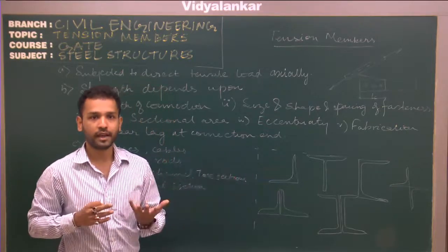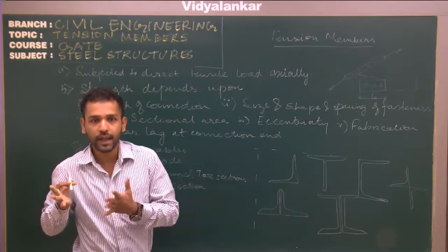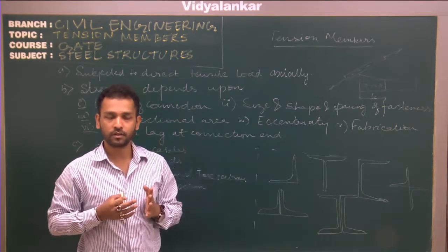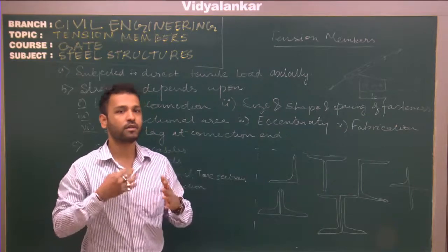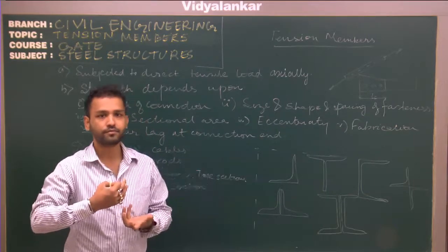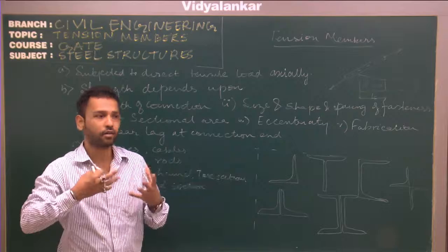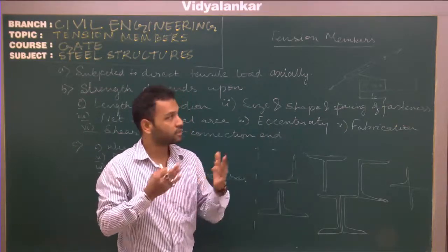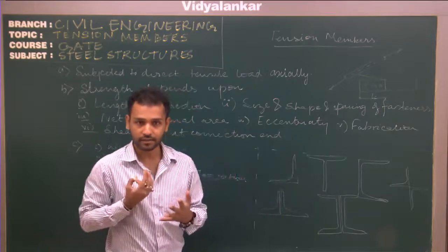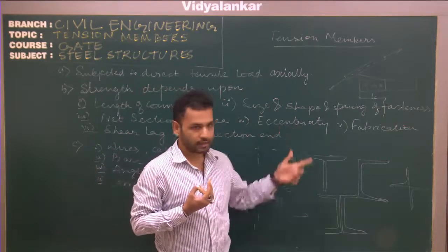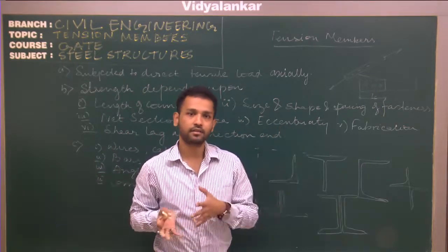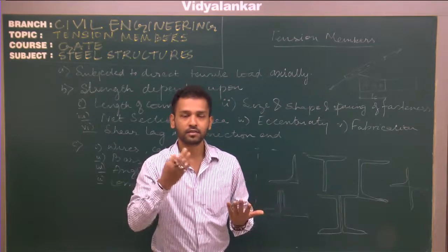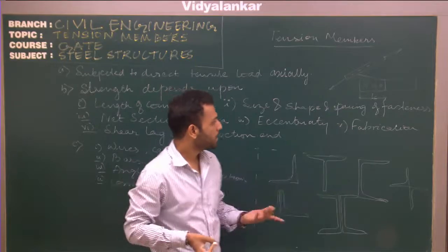If that moment is high, that means an extra load has been imposed on the structure apart from the vertically applied load. That is the eccentricity. So therefore, load plus the moment, so external additional load. If the eccentricity is high, the total load increases and hence the strength taking capacity will decrease, because the additional moment induced in the structure due to the eccentricity will be more.